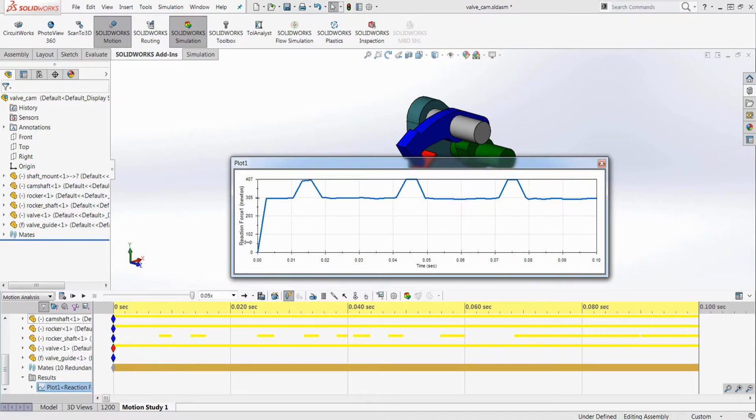You will notice that the force has increased significantly to about 60 pounds, and there's absolutely no chance of separation between the cam and the follower at this RPM. The higher force can obviously be attributed to the increase in stiffness and hence the preload on the spring.